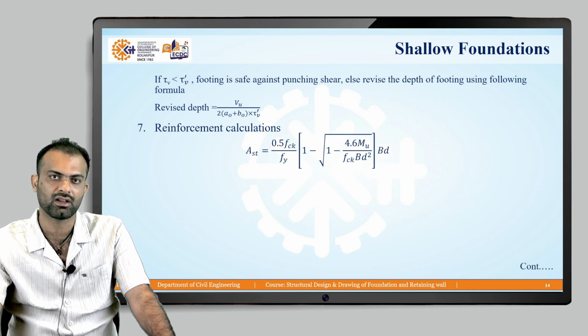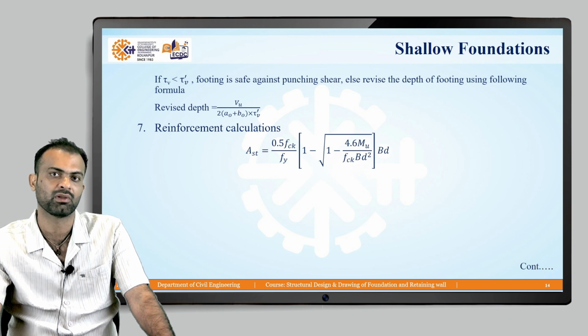If we are designing the reinforcement for the sagging moment, we use the sagging moment we got in the shear force and bending moment diagram. For the hogging moment, we use the hogging moment we got at the middle span between the columns.